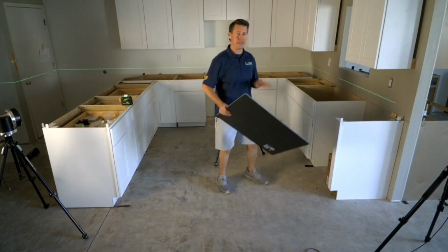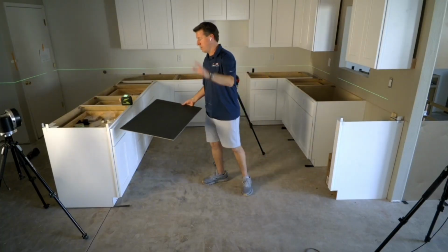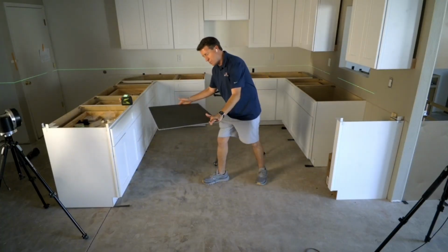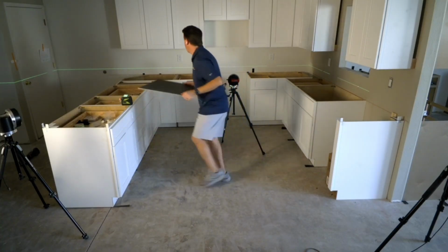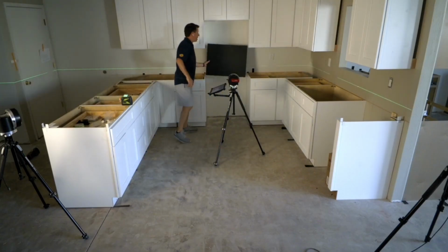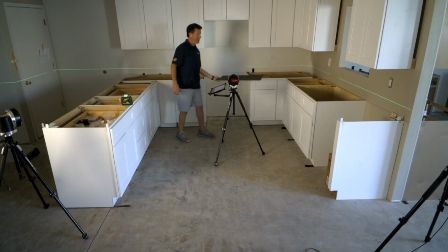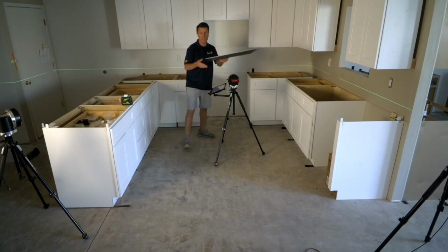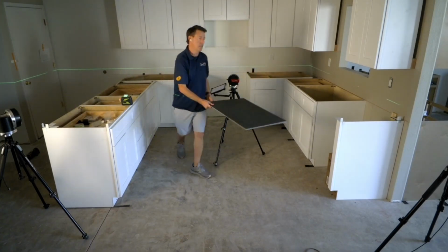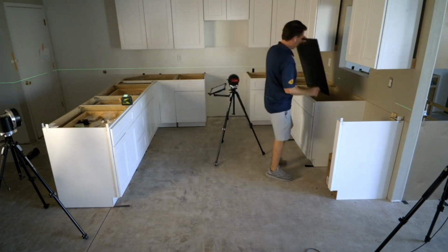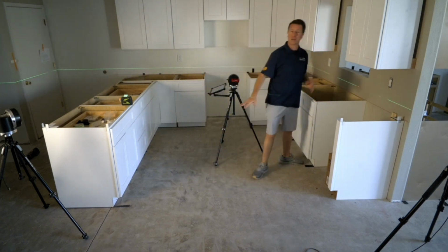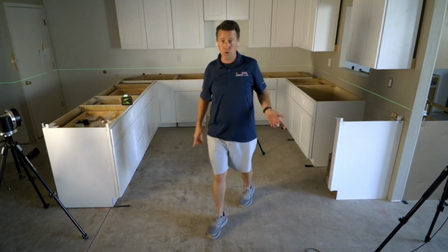I'm explaining this different ways because I think it's really important, right? Today, I'm going to capture a plane right here. Later on, in another job, sometimes I would set my plane on a wall, right? So wherever we put that triangle, those 3 points on the triangle tell the system where we are measuring. And I do want to call out, we don't recommend setting a plane by shooting 3 points on the floor, all right?